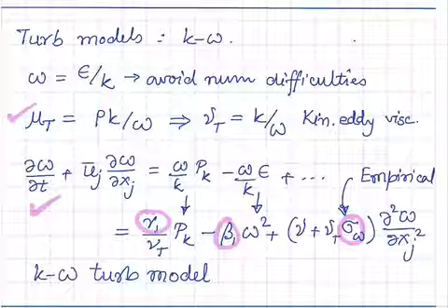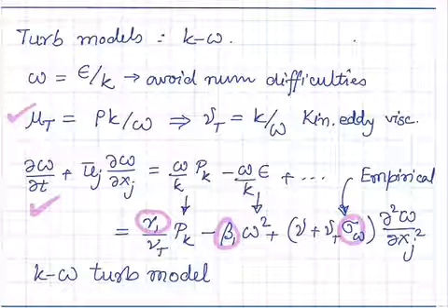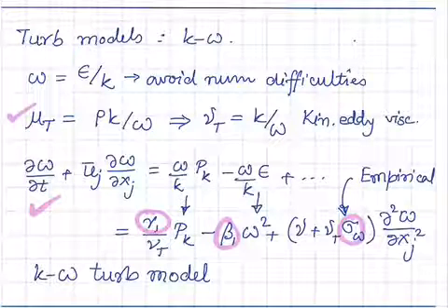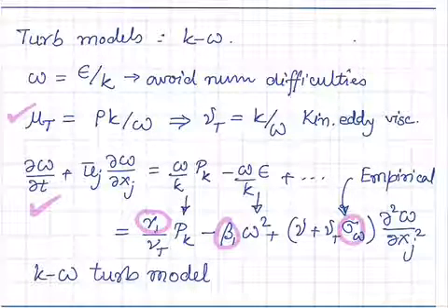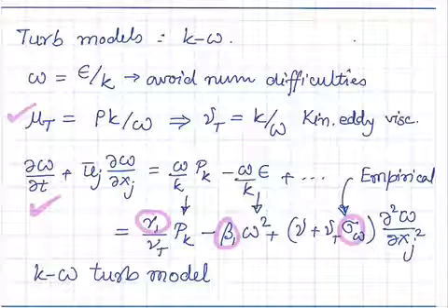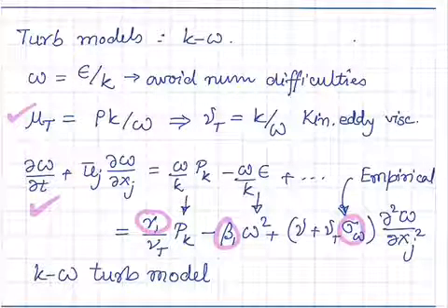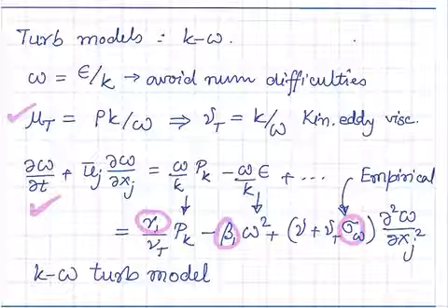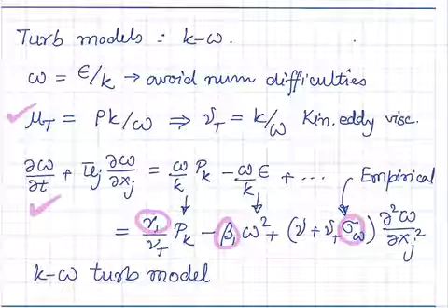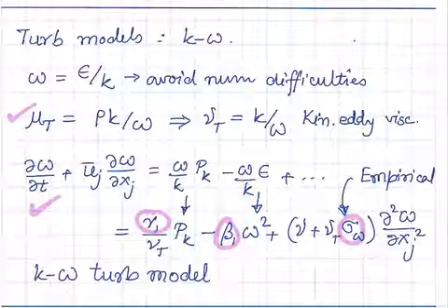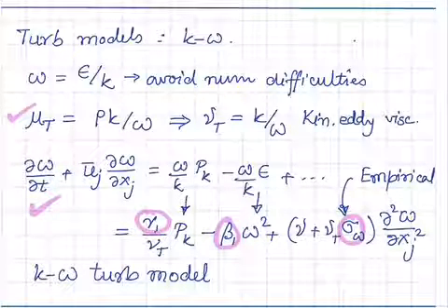There are many different kinds of turbulence models, but overall the ideas of turbulence modeling remain the same: there are 4 mechanisms which can create, destroy or diffuse turbulence, and those are used in different ways to create transport equations, differential equations that can be solved, just like the conservation equations for mass, momentum and energy. Okay, with this we will stop today's lecture.